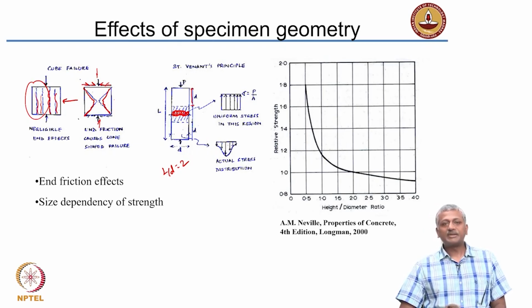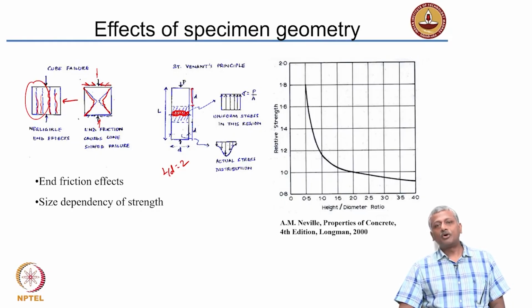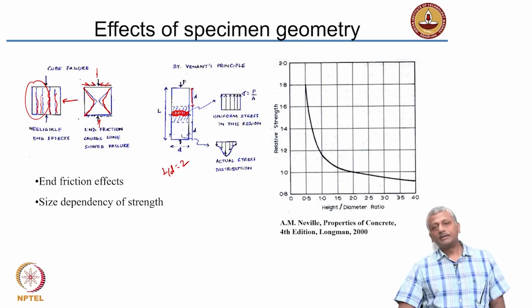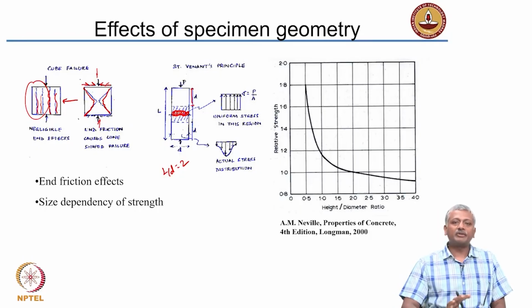Okay. So, because of that, when you do your reinforced concrete design concepts, you learn that the cylinder strength is what is taken for assessing the compressive capacity of a column. Okay. So, please remember that the cylinder strength is the true compressive strength of the concrete. The cube strength is usually 20 to 25% more than cylinder strength.